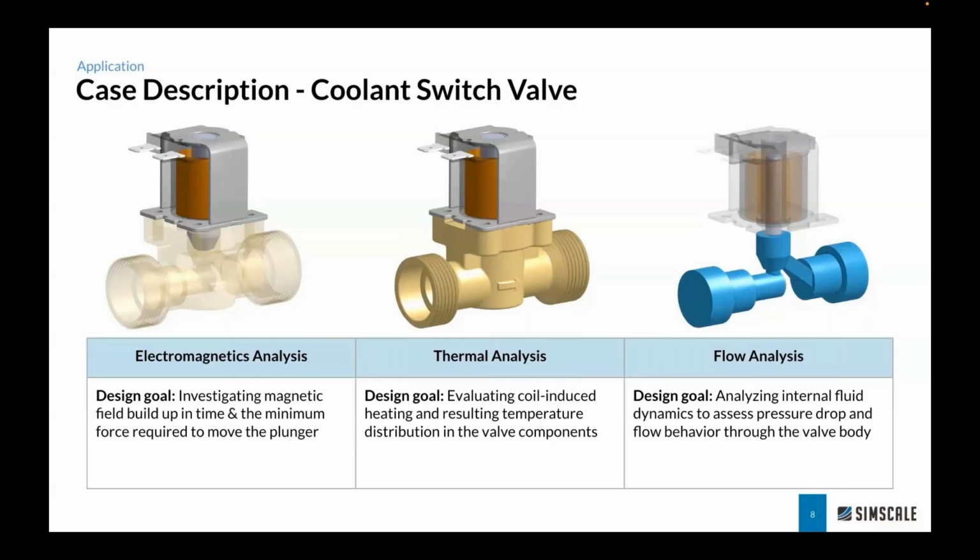And we'll be predicting temperature rise by using ohmic losses from electromagnetics as inputs to thermal simulation in our application today. And that can help us to answer whether the coil is overheating. And we can also have early thermal checks because it's essential to ensure the long-term reliability of this component.